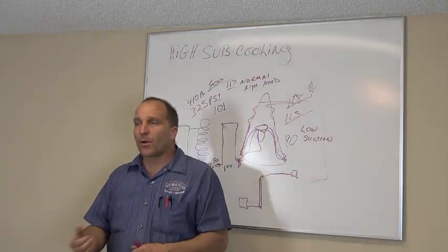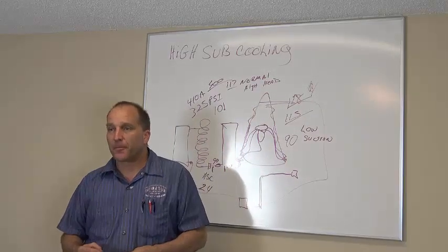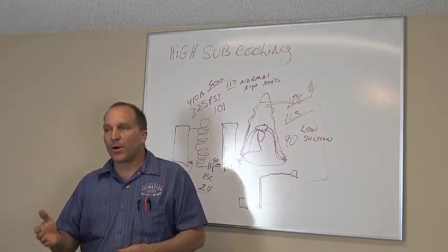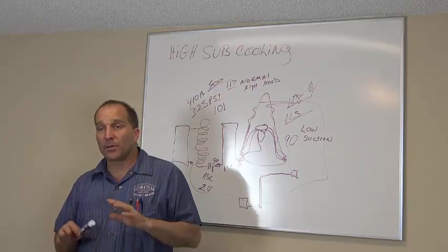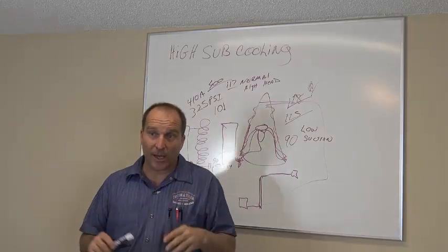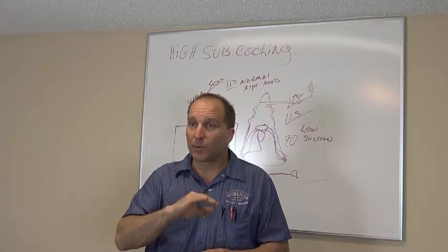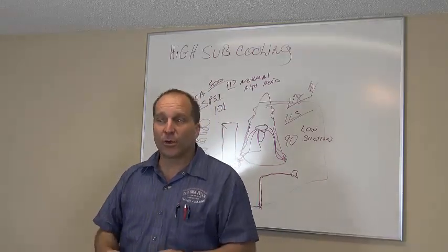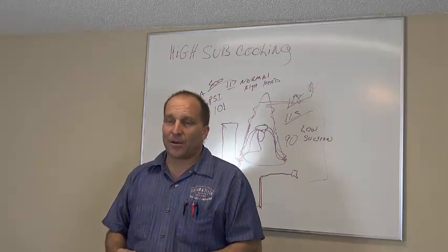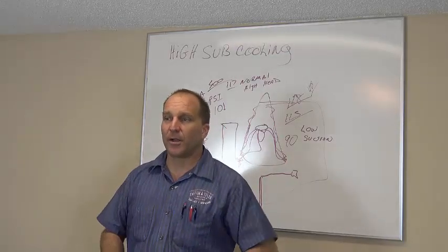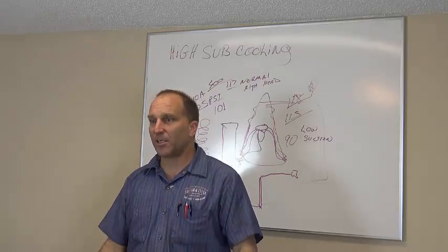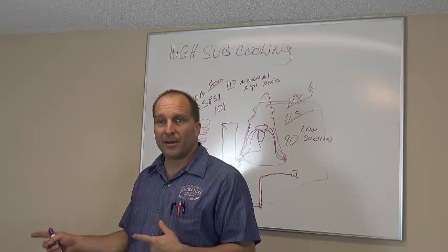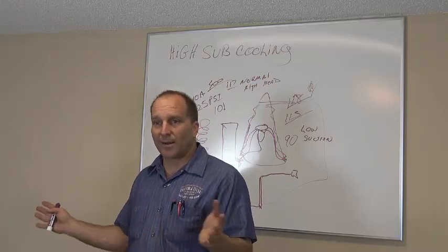As you throttle that refrigerant into the system, you can slowly bring your subcooling up to where you want. Now when you get the proper subcooling, you need to look at your head pressure. Subcooling's right. I know I have a TXV. I'm at 10, 12 degrees on my subcooling. Now you have to ask yourself, what is my superheat and what is my suction pressure? Let's see where we are now, because your system is not charged properly if your suction pressure is whacked out.